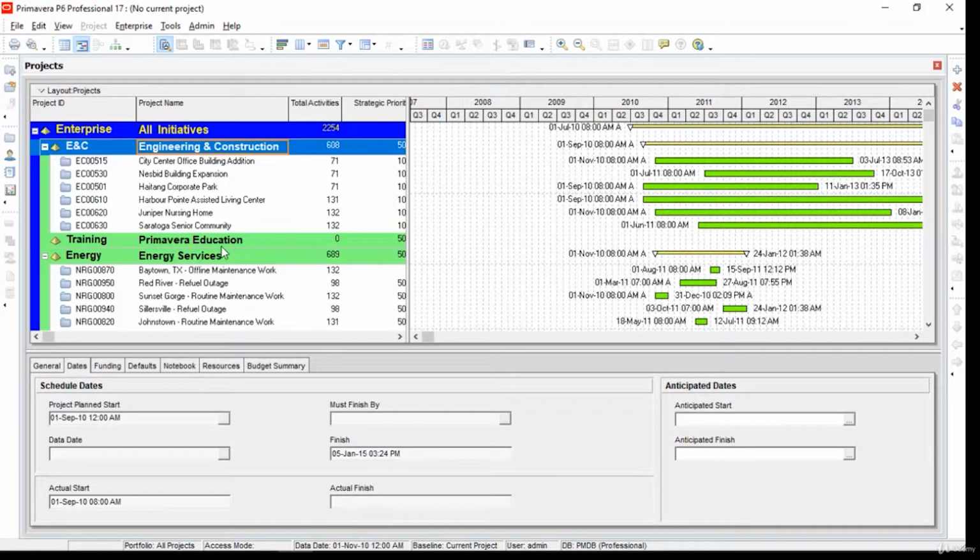Next, we are going to create our project under this new EPS named as Primavera Education. Please remember that the EPS ID and name can be selected as per our own specific company requirements.